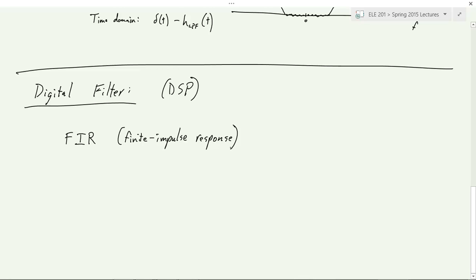So the way that you implement an FIR filter, let me throw out a design that's a very common design for some signal processing, and we'll see why this is a finite impulse response filter. Suppose you have some real-world signal that's going into your DSP processor. You can think of it as sound or whatever's being measured, right? And it's coming in sampled already, okay? So you have x of n as some input. Well, you have some memory units. I'm just going to represent these as blocks with a D for delay. That's going to hold on to one sample for one moment, and out of this will come the sample that was there in the previous time step, n minus 1.